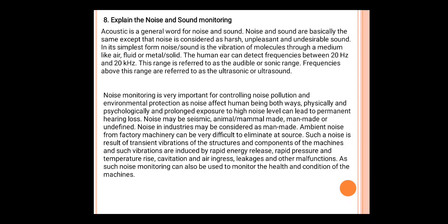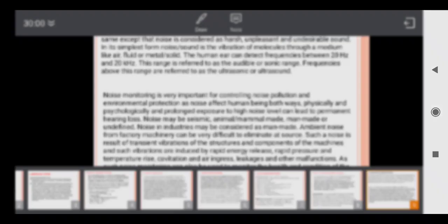Such noise is a result of transient vibrations of the structure and components of the machines, and such vibrations are induced by rapid energy release, rapid pressure and temperature rise, cavitation and air ingress, leakages and other malfunctions. So these are some noise factors. Noise monitoring can also be used to monitor the health and condition of machineries. By monitoring all these things, noise and sound monitoring can be done. This is all about the 8th question.